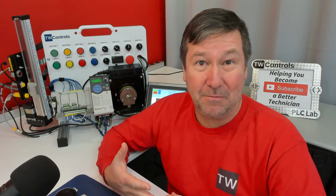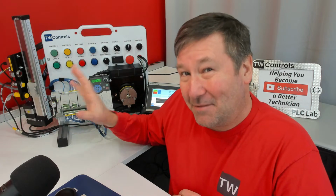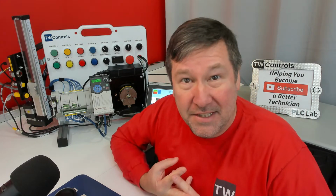Using Ignition, we can trend it to some type of SQL database or somewhere where we can come back and retrieve it later. The other really cool thing about doing it this way is we don't actually have to have the software to trend this. It's not a big deal in Connected Components Workbench because it is free. But if I was using Studio 5000 or TIA Portal, then I can set up a trend to do some troubleshooting without actually having the software present. So a lot of good things there.